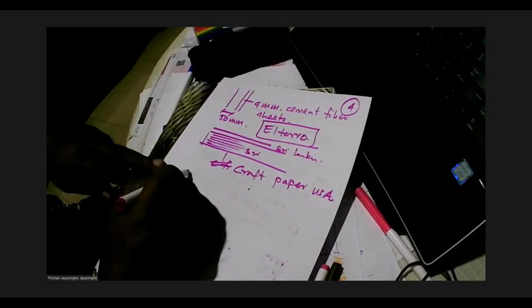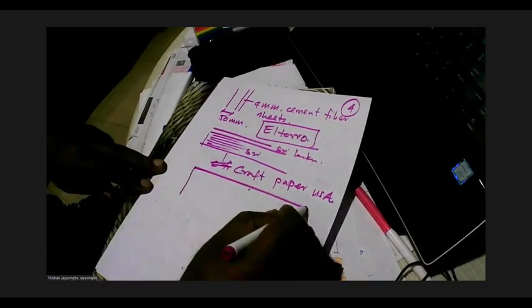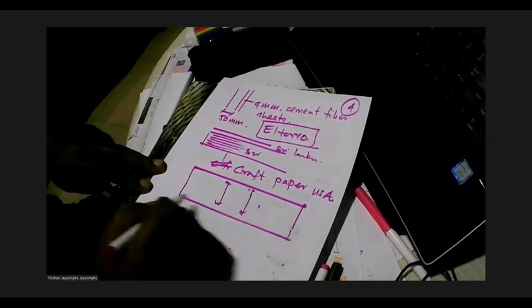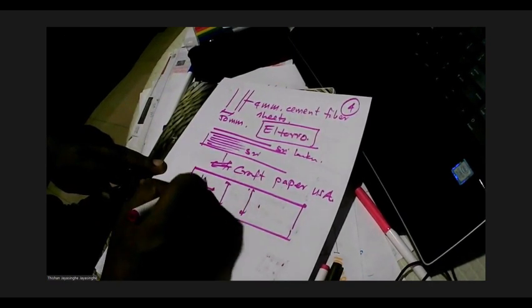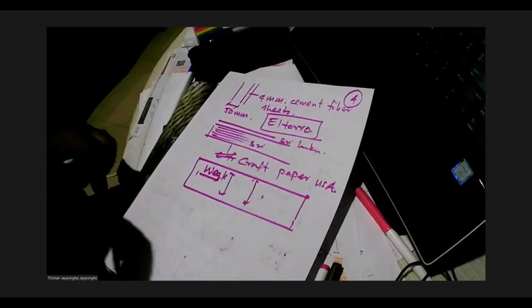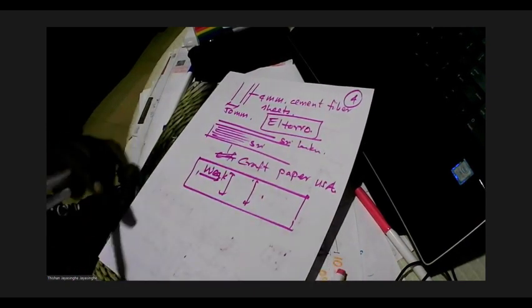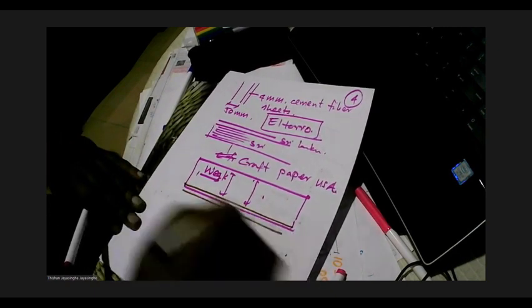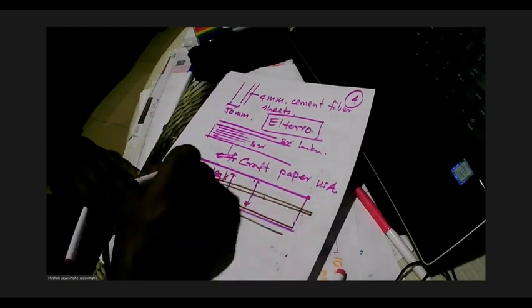Very strong, and what you have to keep in mind is it is strong in this direction, but very weak in this direction. So always make sure when you are using a Dura panel, you support it here, support it here,